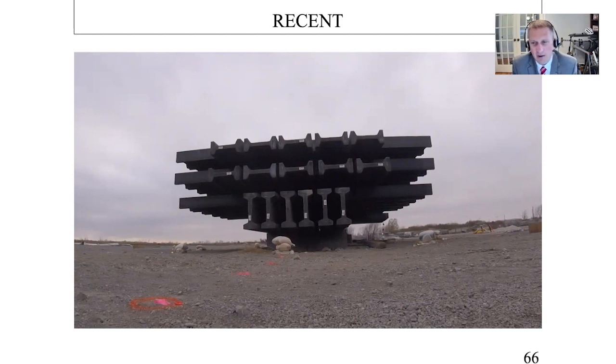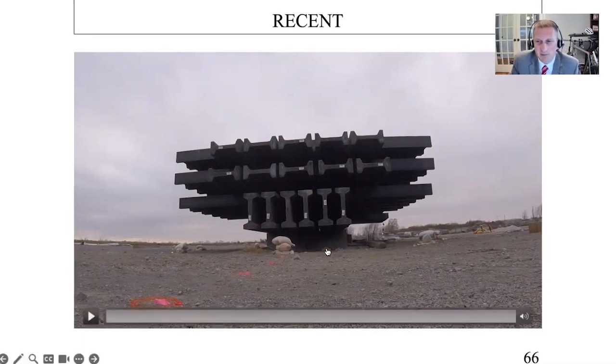And so we drove a pile group, and we actually drove two pile groups. One's an H pile group, and the other is a pipe pile group. The H piles that were driven, within this cap here, there are 7 H piles that are 14 by 102s and 85 feet long. Behind this, and I'll show you from a different camera angle in just a second, you'll see some pipe piles that are 18-inch in diameter, driven closed-ended and filled with concrete.